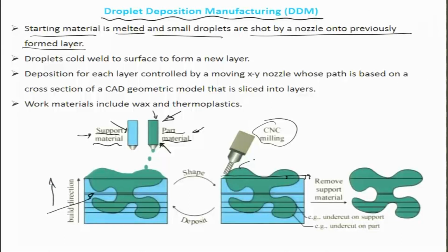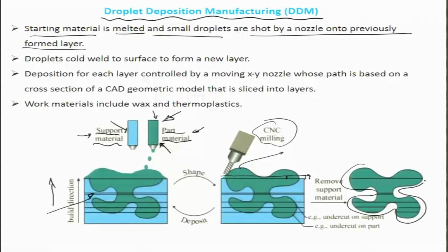So once this extra material has been shaved off, the layer is prepared for the next round of printing, where the next slice, which comes as information from the CAD package, gets laid out in terms of areas coated with wax and areas coated with a solid material. Obviously, in a layer by layer manner, a very complex part like this can be built, every time milling it and shaving it to the intended layer thickness.